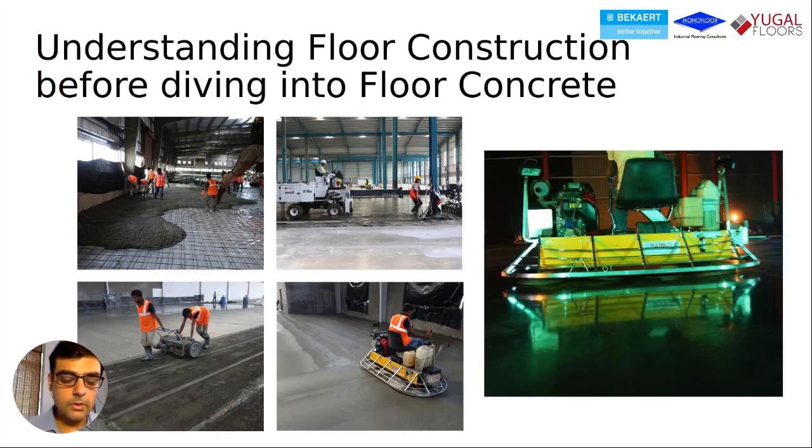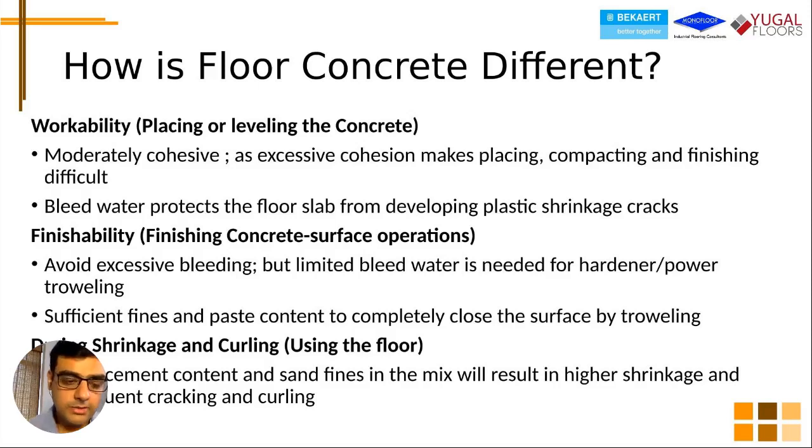I think next up should be concrete. All right, so before we get into concrete for flooring, I would like to spend some time just explaining the process of flooring. So the first picture is the guys placing the concrete. Second picture is they're using leveling equipment. There are several. What I have shown you here is a laser screed. Third picture is spreading or broadcasting hardener in the initial stages of finishing. Fourth picture is closing the surface. And finally, the biggest is the nice glossy finished floor that comes as an end result of all these sub operations.